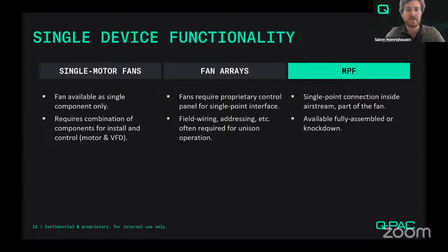With the fan arrays, it depends on how you've set it up, but a lot of times if you have multiple VFDs, or multiple pieces that have to actually work together or be controlled separately from one another, then that takes away from the single device functionality. But the multi-motor plenum fans, they act as a single device.